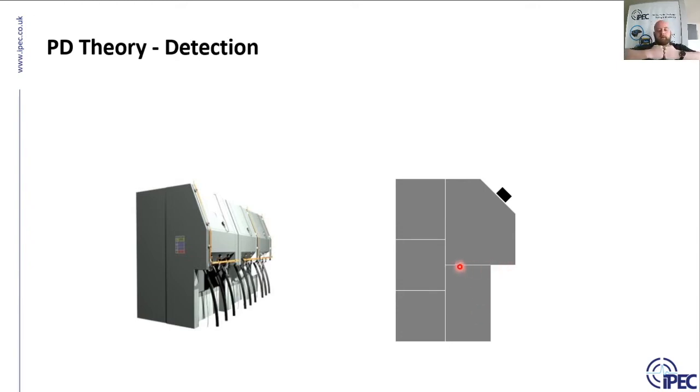So where two panels are attached together, it travels out through the gaps and along the outer surface of the equipment. So it travels along the outer surface of the equipment, and then it travels across the surface of the TEV sensor, be that either built into, like I said, built into an instrument or physically attached. And then that signal is induced on the sensor.